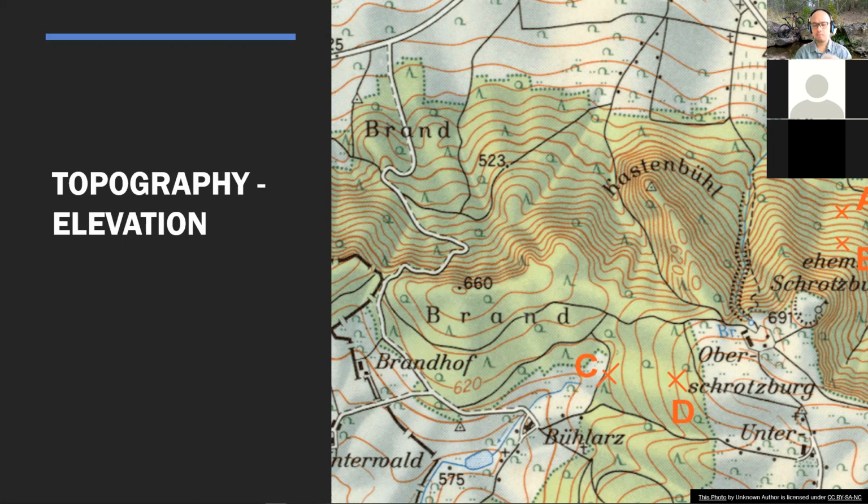Elevation data, as I've briefly demonstrated before, are portrayed on topographic maps as contour lines and spot elevations. For site planning purposes, an effective way to visualize topographic relief is to create a choropleth map of elevation. It's basically a colored contour map. The technical term for it is a choropleth map.